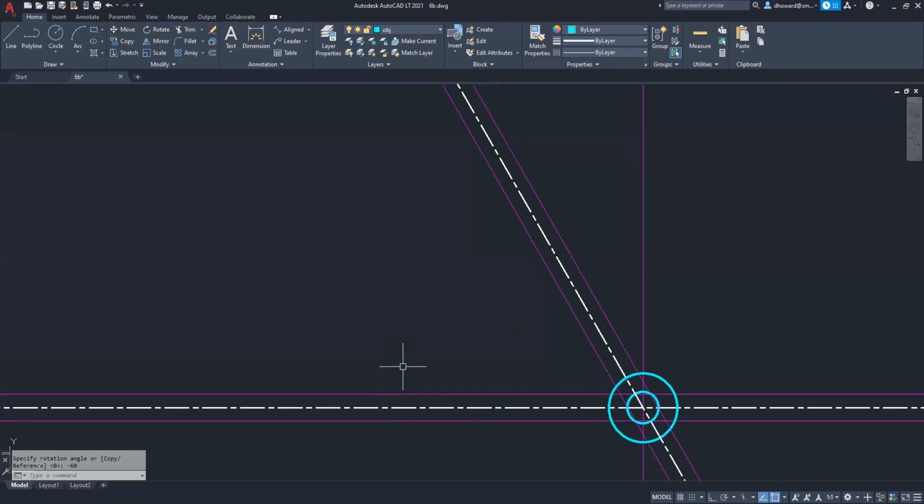We need some vertical lines. So on this bottom arm, I'm going to offset this vertical line going through the center 4 and 19/30. That is off the drawing. I'm going to offset it 4 first. So O, enter, 4, enter. And the reason for that is 1, it's easy to do, and 2, it's also required of the upper view. So I need to do a 4-inch offset there.